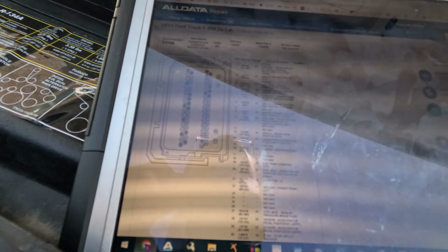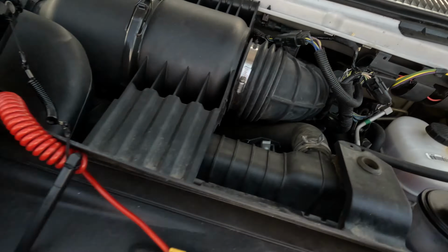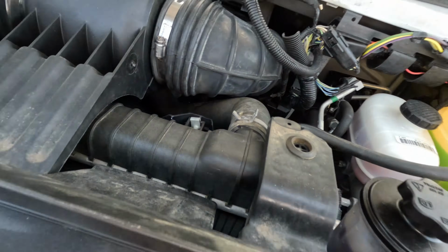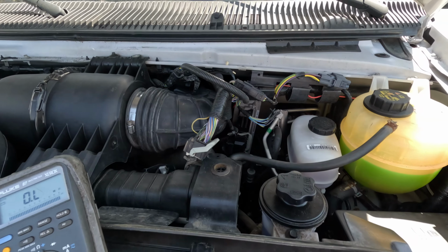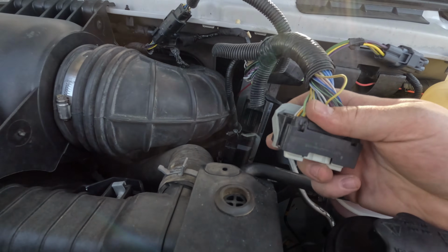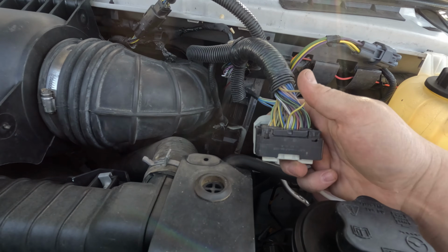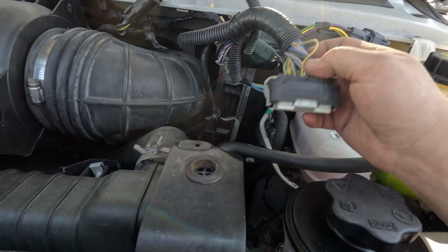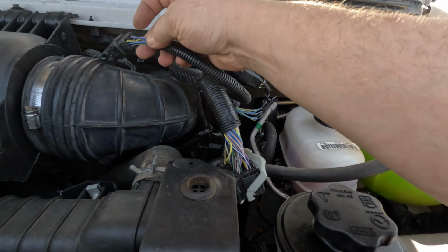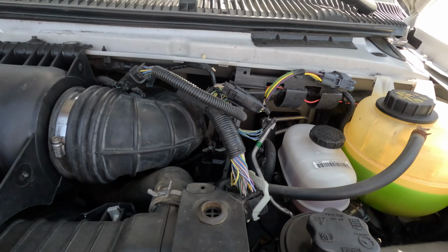Alright, here's the connector view. The black one. Okay, so let me get to the computer. Because it's at the computer, and then we'll back up. Okay, so here's the connector. And this is pin 58. This white, this yellow, and brown wire. So before I plug it in and test for ground, I want to check continuity from here to here. Or to there, doesn't matter.